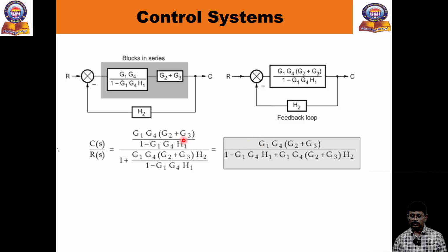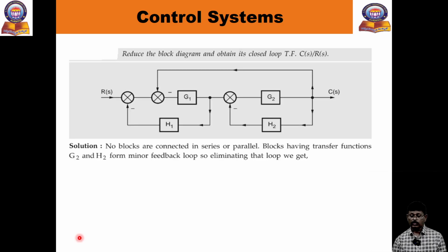Now simplify the equation. Take the LCM, simplify the equation. Then you will get the transfer function of the block diagram. See how simple this technique is. So this converts to a single transfer function of the block diagram. So again, take another example.